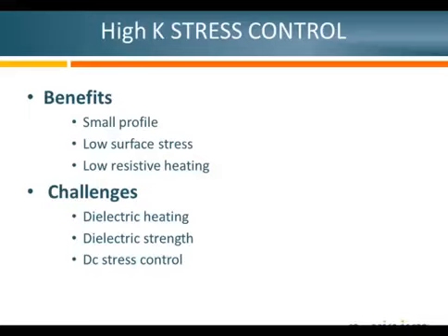So therefore, you can get the same performance out of a shorter termination because you have lower electrical stress. With lower electrical stress on the surface, you also have less chance of tracking. Reduces the risk of tracking and other issues with the termination.